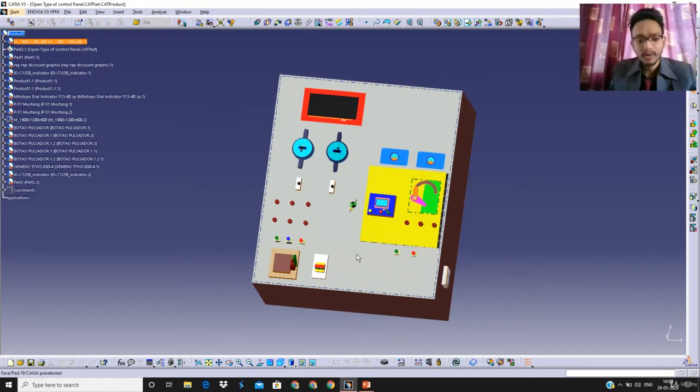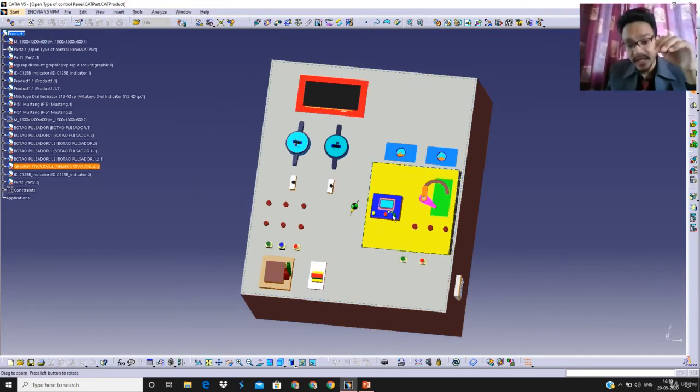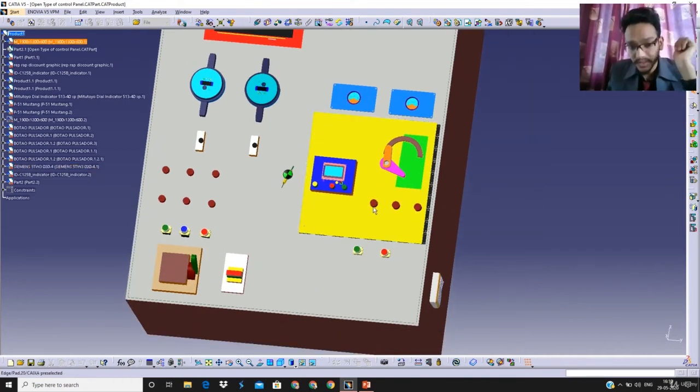But you also have to consider that the panel should operate for DC series or shunt motor load testing or speed control testing. At the right side of the section you can see there is a 3-point starter. Here is the L, F, A terminals: L is the line terminal from which you give the live connection, that is the positive, F is the field terminal of the winding of the DC motor, and A is the armature winding connection. So this is a 3-point starter.